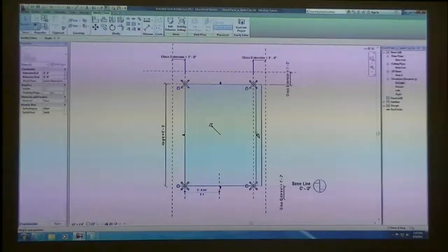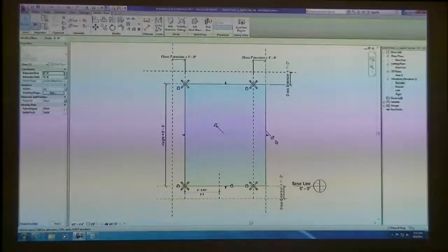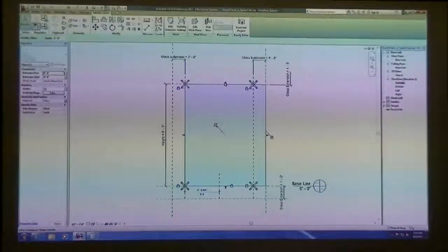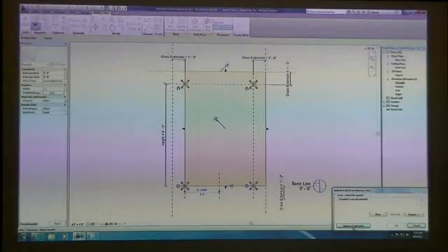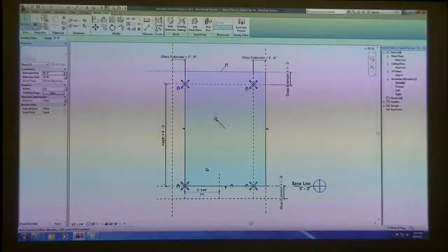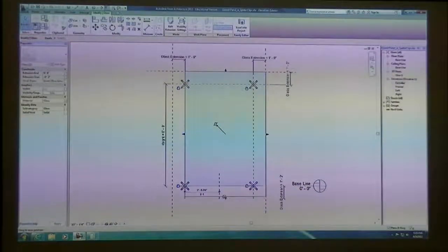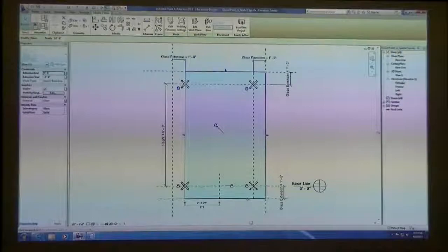But if you drag the drag handles until you snap to the next grid line, that's where I'm going to lock these panels. And every now and then you'll get a constraint's not satisfied. You've got to remove the constraint. Go ahead and do that. Do the right side, the top and the bottom. Remember to lock.